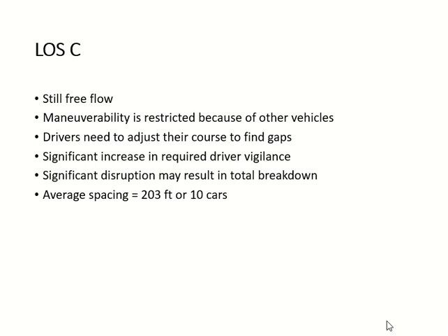Level of service C, still you are going at high speed, but your maneuverability is restricted because of other vehicles. So in your lane you can go at high speed, but when you want to change your lane, you may have to wait for the other drivers to give you the chance to do this. Like you want to change your lane, most of the times you will not find the space. You may have to slow down or speed up to find your space in the other lane.